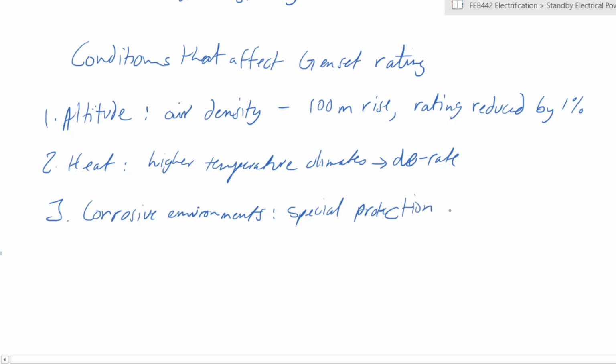This would generally mean that if you have a thicker or more durable layer of insulation or paint or protection on the machine, it can dissipate heat at a lower rate. So you have to derate the machines due to any special protection. So you derate.